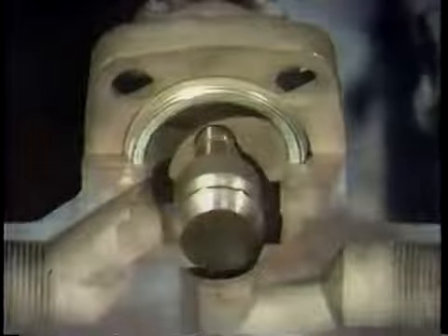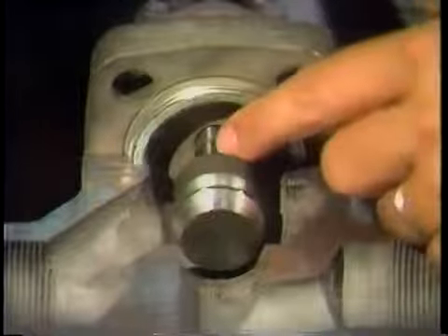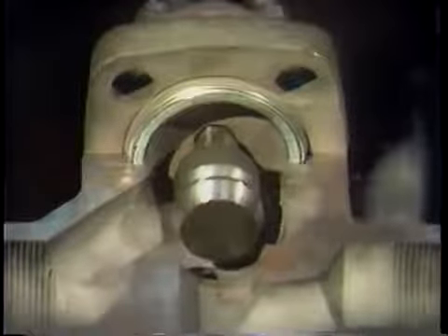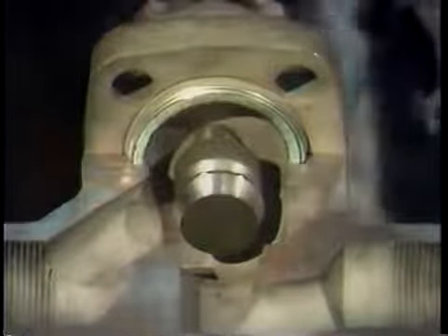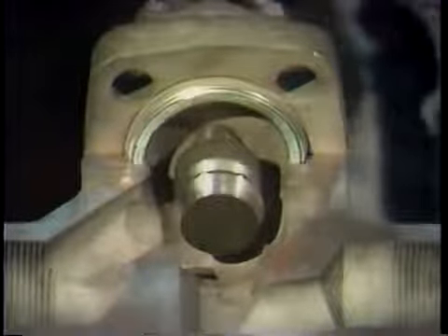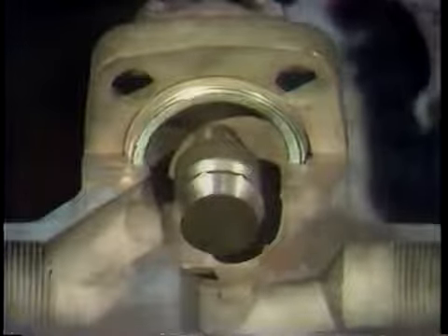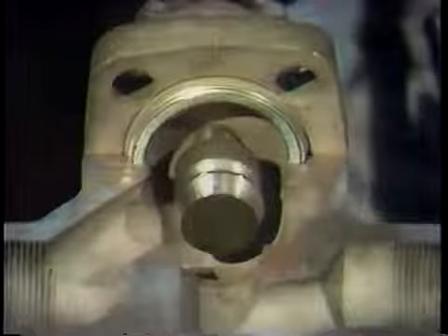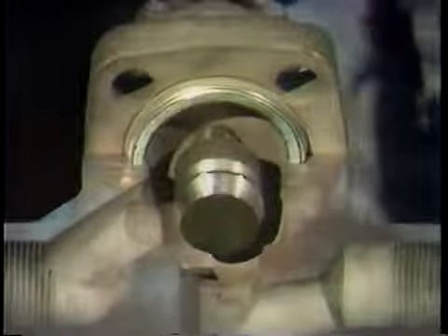Many globe valves are made with a seating area above the disc, like this one. It's called a back seat. When the valve is fully opened, the disc will seat against the top of the bonnet. This keeps system pressure off the packing. Manufacturers advertise that packing adjustments or repairs can be made while the system is pressurized with the valve on its back seat. However, for personnel safety, we recommend that you do not perform valve maintenance while it is under pressure, even if on the back seat.